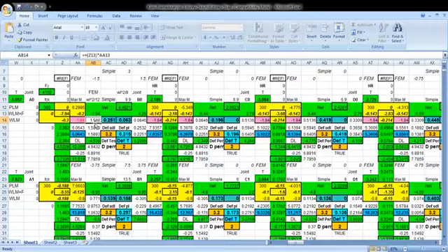This is a very important point. We cannot move to other joint until we understand this. We have just started calculations of forces, calculation of moments at joint number 1, or A0. Beam and column are involved in this. This is load here, sum of these two, and this is the rotation contribution factors from that table in the beginning. This is multiplied by this, and we get this; the signs it will take automatically. So this is one cycle.